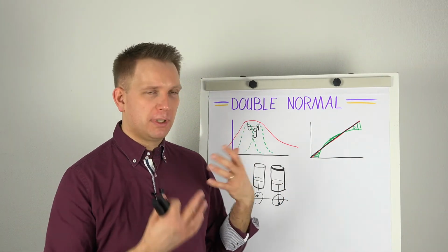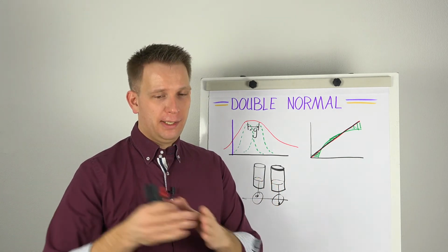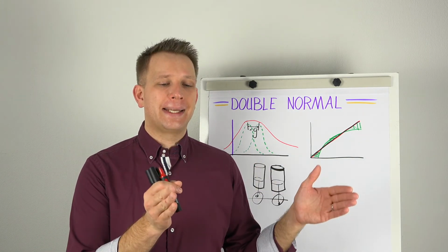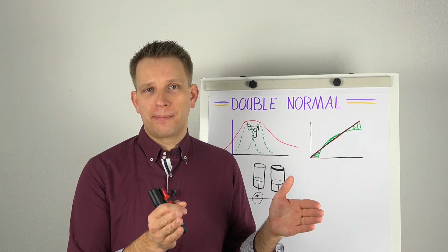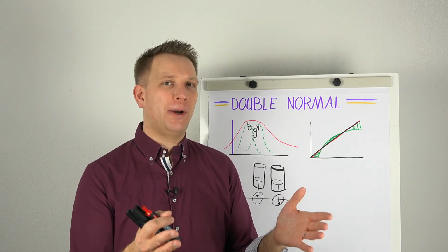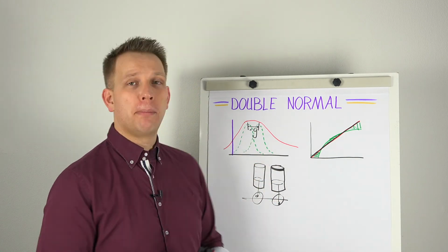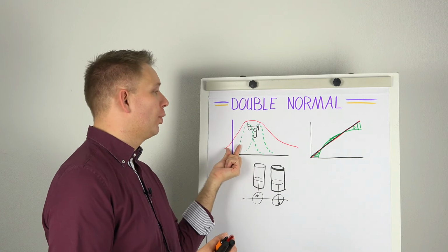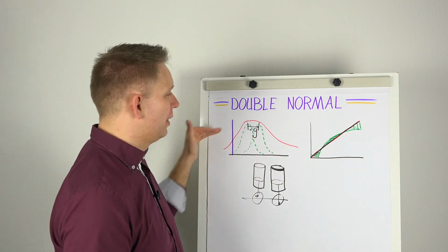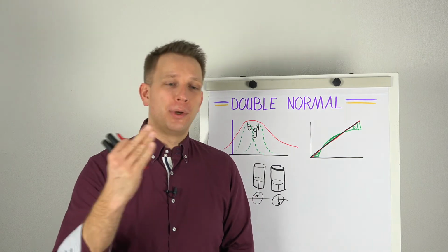The same type of process will also happen when you are slicing a big product in nice and equal slices, so a very nice, strict, normal distribution, and then the end cap is registered also as a slice. It's not completely correct, but most machines don't really sort it out. So they will also weigh that end cap, throw it away, but then you get a secondary, much higher, or sometimes much lower distribution. And what can even happen is that you get both of them, right? High and low, and then you just get a broad distribution,